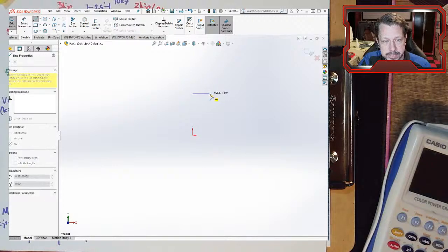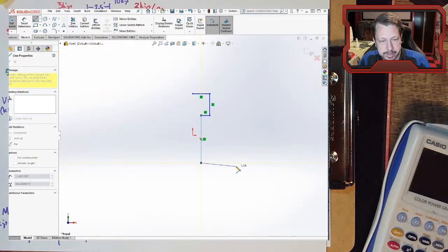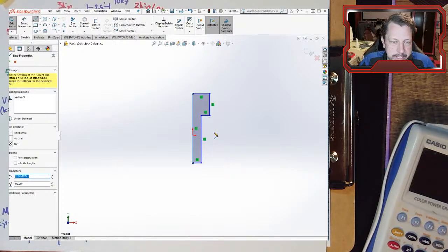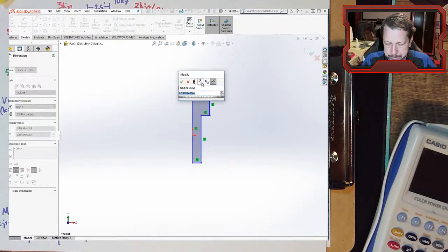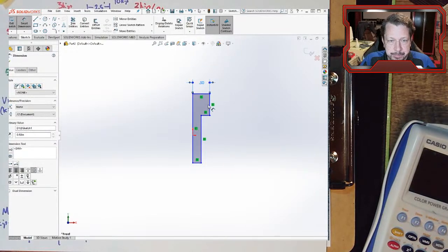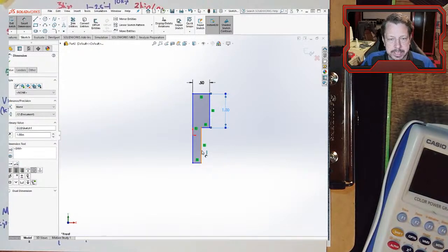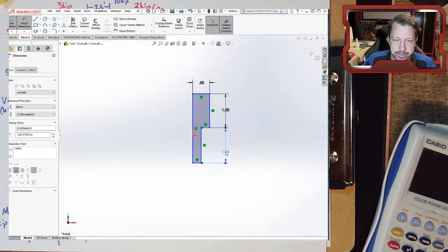So here's how I'm going to build the shape. It's going to come off the center, and we'll dimension it in a second. So I'm just going to give it some rough dimensions right now. Something like that. Let's close that shape so that it's 1/4. This is just 1/4 of the shape. Let's dimension this. When we cut these out in the course, this is probably 1 inch, so let's make that 1/2 inch. This is the little tab that would mount into the machine. Let's make it 1 inch long. This is half of the gauge length of the material. Let's make it 1.5 inches.